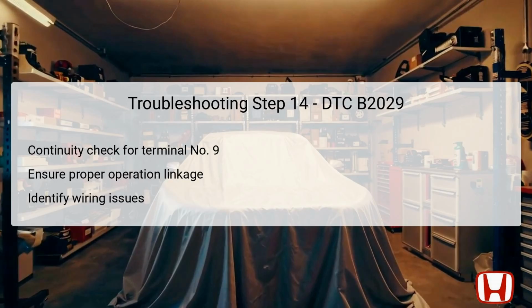If continuity is confirmed, it is likely that issues may reside within other components, like the control unit or the remote control assembly itself. However, if continuity is absent, further investigation of the wiring must be undertaken, looking for shorts, breaks, or corrosion that could impede function. This thorough check is essential for comprehensive diagnostics to restore reliable operation to the sliding door systems in the Honda Odyssey model.